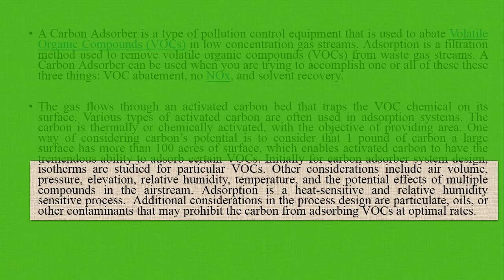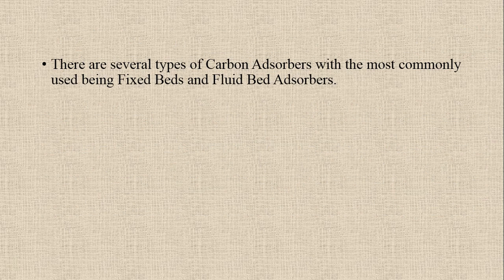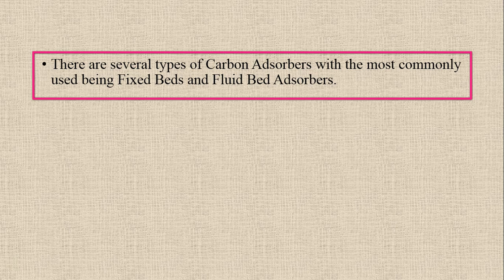Adsorption is a heat-sensitive and relative humidity-sensitive process. Additional considerations in the process design are particulates, oils or other contaminants that may prohibit the carbon from adsorbing volatile organic compounds at optimal rates. There are several types of carbon adsorbers, with the most commonly used being fixed beds and fluid bed adsorbers.